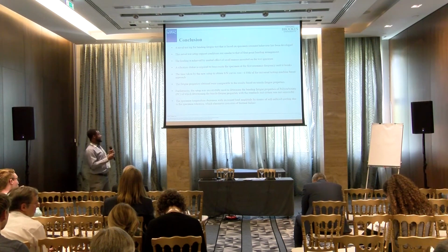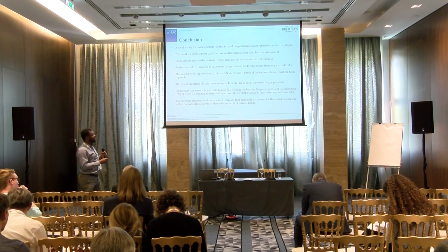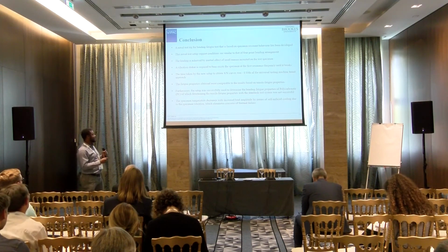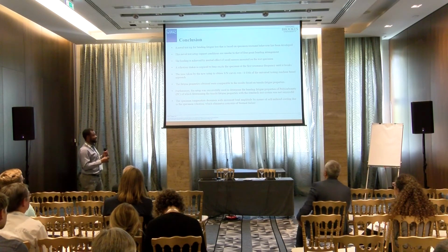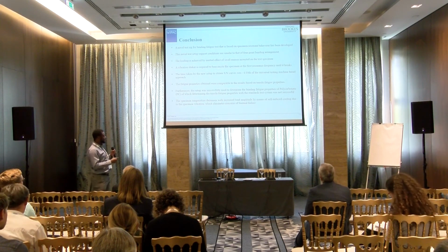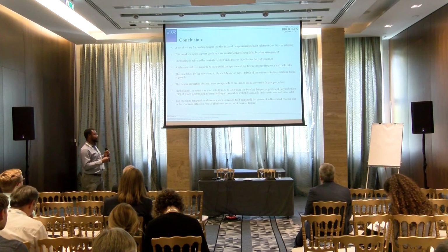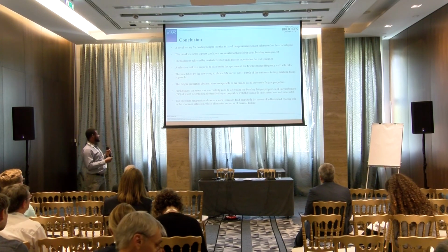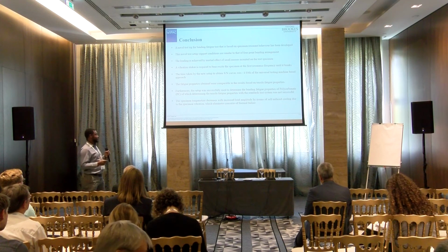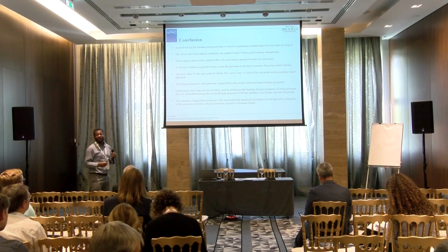Furthermore, the test setup was successfully used to determine the bending fatigue properties of polycarbonate, for which determining the tensor fatigue properties with the standard test system was not successful. The specimen temperature decreases with increased load amplitude by means of self-induced cooling due to the specimen vibration, which eliminates the concern of thermal failure.